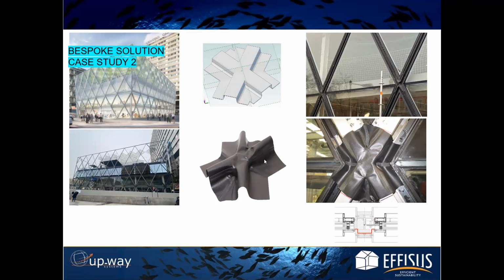This one is a different project that we have developed in Madrid with Norman Foster, and they had this crossing shape here that they needed to apply an EPDM on. And so, as you can imagine, to do this type of seal in a proper way at site, it would be almost impossible and with very poor quality, because there are many weak points here on this ceiling. And so having these 3D prefab pieces in all of the facade intersections allowed us to develop a perfect weatherproofing seal here.